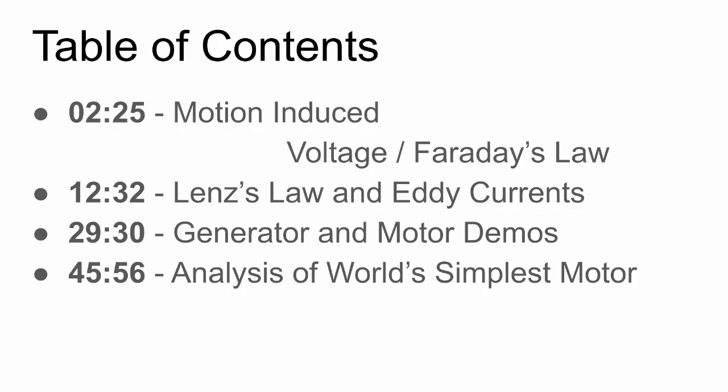And this law is what we introduce as Faraday's law, which says that a changing magnetic field induces voltage. And we discuss a separately named law, Lenz's law, which helps us figure out the direction of the induced voltage. Lenz's law is essentially the name we give to the minus sign in Faraday's law. It is a way to conceptually understand the effects of eddy currents, which slow down the motion of conductors moving in a magnetic field, or magnets moving near a non-ferromagnetic conductor.